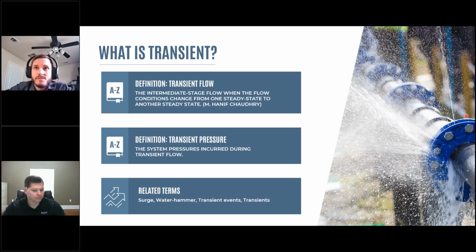It travels much faster too. It's like a very, very fast acting slinky. As you may remember, Joukowski's instantaneous water hammer equation describes the pressure response to a change in velocity as being dependent on two other variables: fluid density, rho, and wave speed, c, also called celerity.